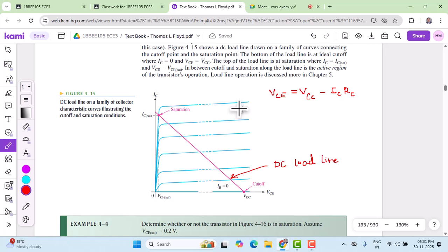So VC max is given, IC max is given, PD max, all data ratings have been given here for the circuit which is shown. And we need to determine the maximum value the VCC can be adjusted to without exceeding the ratings defined here. The VCC is nothing but this supply voltage to be applied so that we are not violating these ratings. And which rating will be exceeded first? We'll see which rating will exceed first, whether the VCC or the product of these. We'll see that.